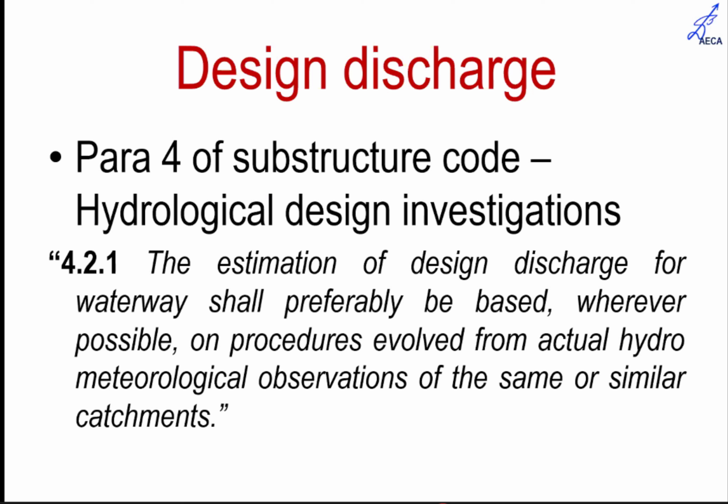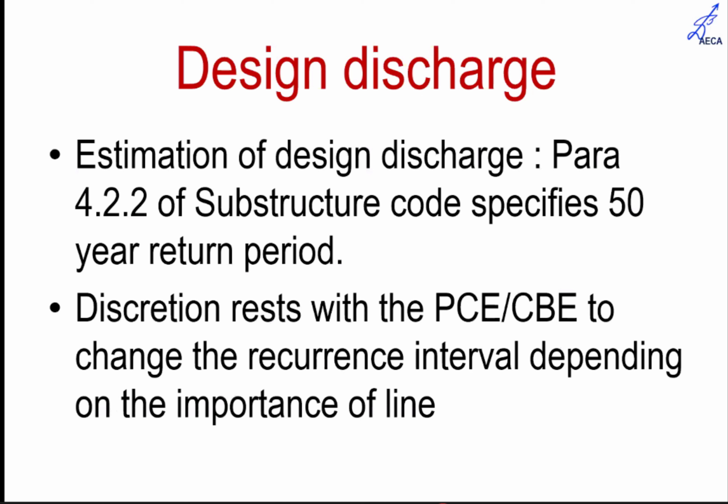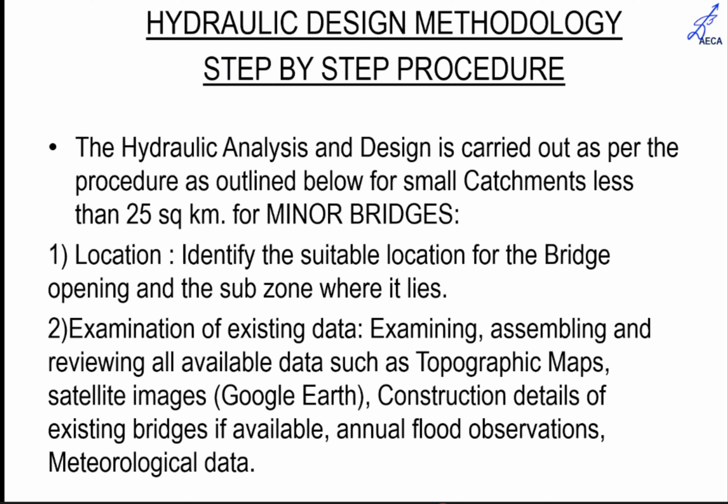What is the definition of the design discharge? For hydraulic design investigations, estimation of the design discharge is to be based wherever possible on, or evolved from, hydrometeorological observations of the same or similar catchments. The IRS substructure code specifies a 50-year return period for the flood estimation and the discharge estimation. The discretion rests with the principal chief engineer or the chief bridge engineer to change the recurrence interval depending on the importance of the bridge or the importance of the line.